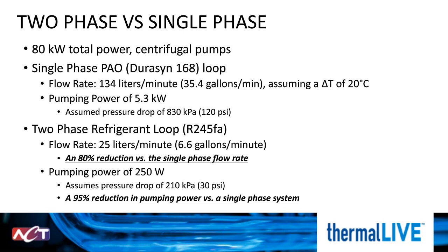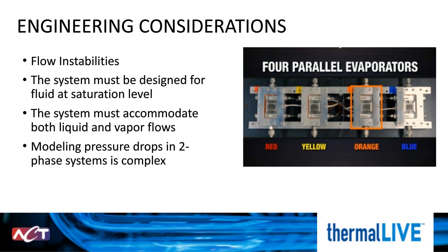But there certainly are things to consider when applying these systems. Since the fluid must enter at saturation, managing flow instabilities and pressure drops is a concern. The design engineer must be knowledgeable on the change of pressure as the system increases in complexity. The picture to the right of the screen is a snip from an ACT video that shows the performance of a pumped two-phase system as parallel evaporator plates are turned on and off. This video is accessible via ACT's webpage.